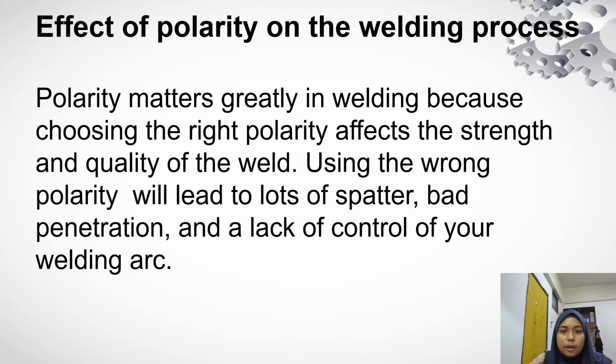Effect of polarity on the welding process. Polarity matters greatly in welding because choosing the right polarity affects the strength and quality of the weld. Using the wrong polarity will lead to a lot of spatter, bad penetration, and a lack of control of your welding arc.